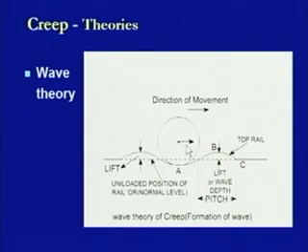Now, the same thing will be happening with the rest of the wheels which are placed on the rail section. So, it means at a number of locations the same type of phenomenon will be happening. Now, as soon as this wheel starts moving in the forward direction, this sort of reverse curve condition will start moving in the forward direction longitudinally, and due to this movement of this section which is being shown here in this curved form, the creep will be induced.